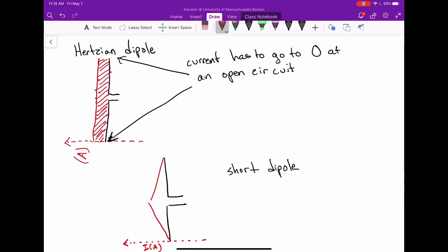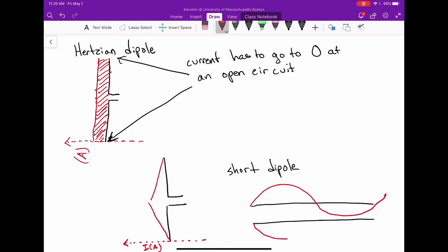On a transmission line, see, it all comes together in the end, that is open circuited, the current goes to 0 at the end, and you get a current standing wave that looks like this. And on the negative wire, your current standing wave is doing the same thing but with opposite polarity. So the current on the upper conductor is going to the left, the current on the lower conductor is going to the right.